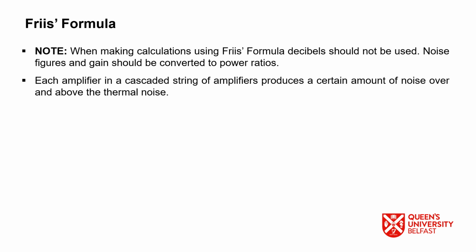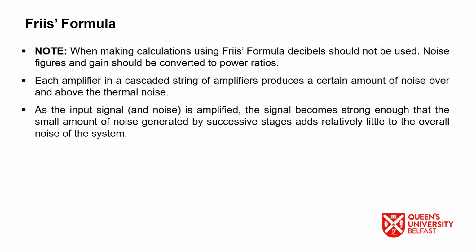Each amplifier in the cascaded string of amplifiers produces a certain amount of noise over and above the thermal noise. As the input signal and noise is amplified, the signal becomes strong enough that the small amount of noise generated by successive stages adds relatively little to the overall noise of the system.